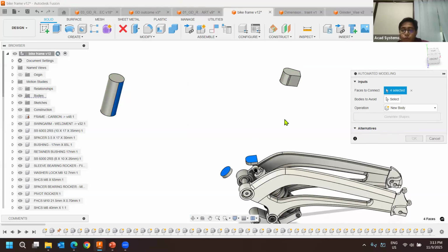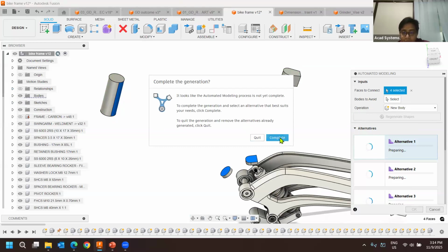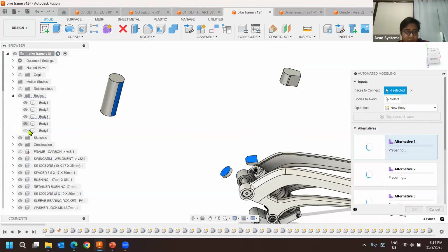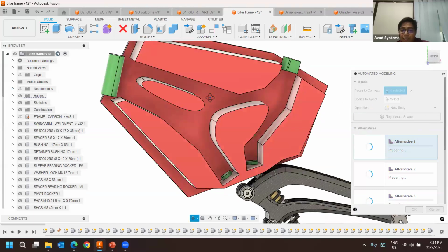If you remember before, for generative design, we had bodies or obstacles that you can select. We also have this body to avoid. If you want to, you can turn it on. Let me just leave it complete first. But maybe I'd like to add some obstacles so that it will not penetrate this area.